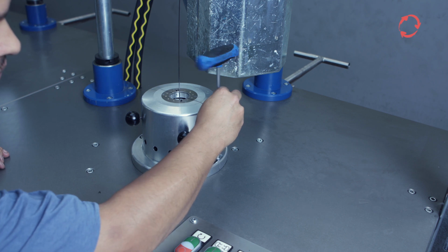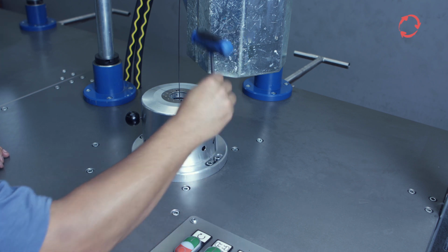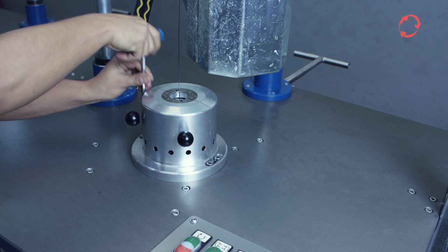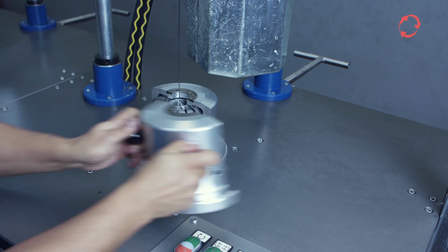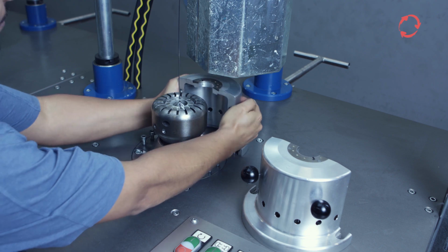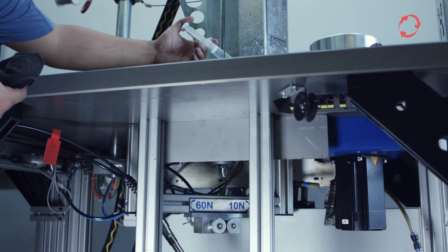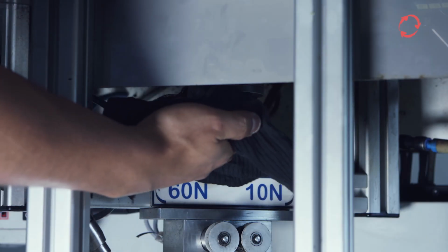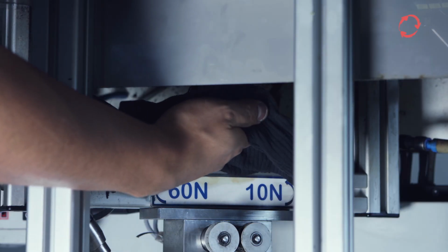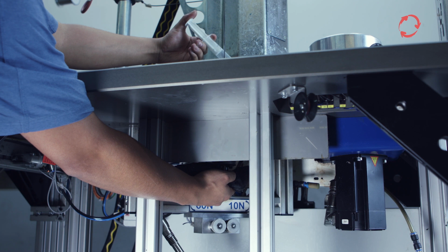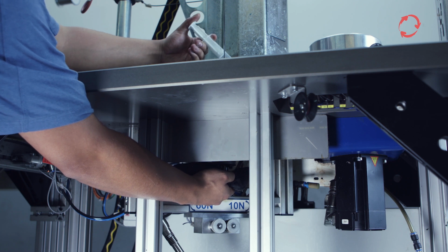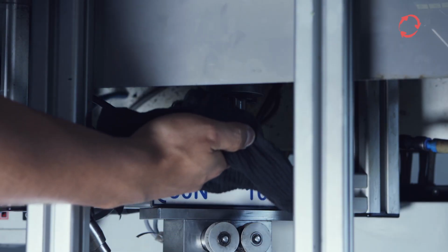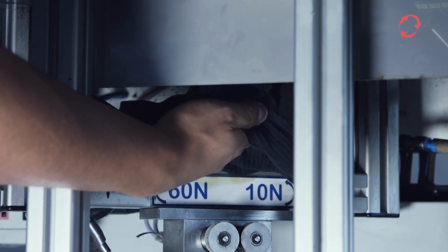To clean the winding head, open the winding head and pull off the front and rear covers. Then clean the thread guide channels with acetone. The acetone has to be injected with a syringe into the thread outlet. Keep acetone about 1 hour in the winding head before blowing out. Keep a cleaning cloth pressed against the head on the bottom end. Ensure that no acetone drops on the sensors.